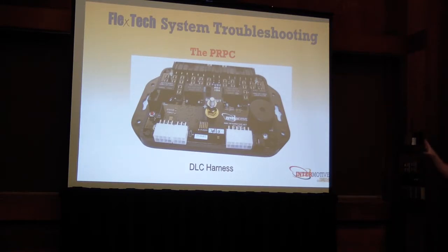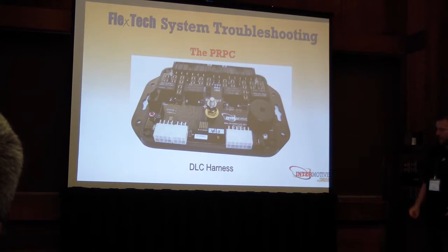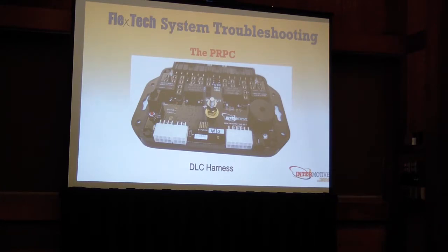All functions are based on the communication there. So we'll have a T harness down at the OBD2 port, and then an extension harness that runs up to the electrical panel, provides power around PRPC, and then connection to one or possibly two vehicle communication networks, CAN. And that's on J19. There's the white 6-pin connector there. So if I grab this module, it's the 6-pin connector J19.